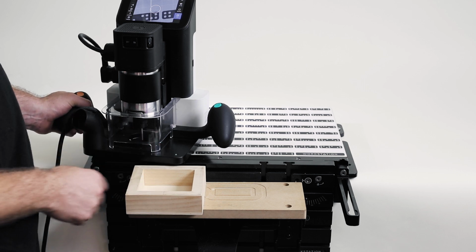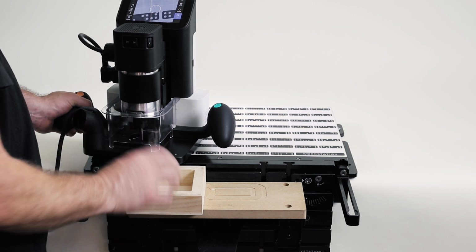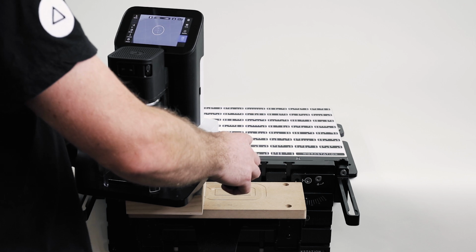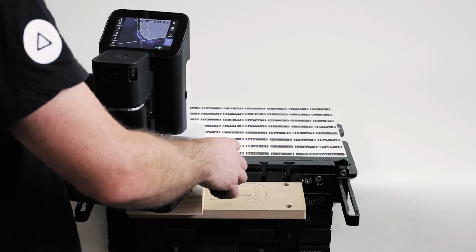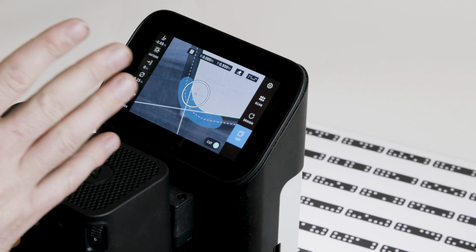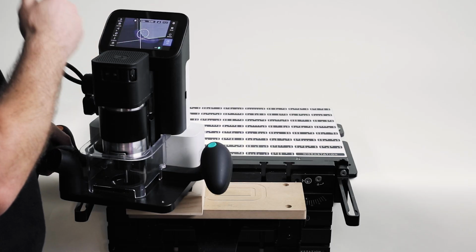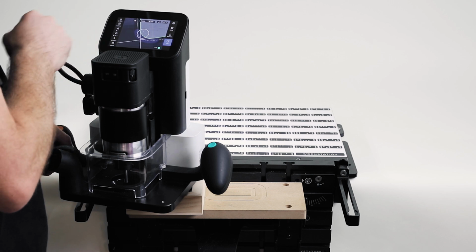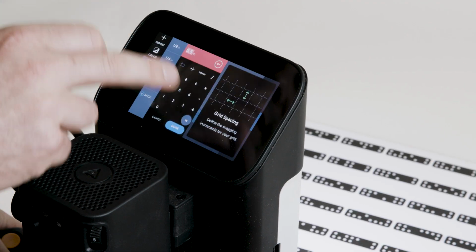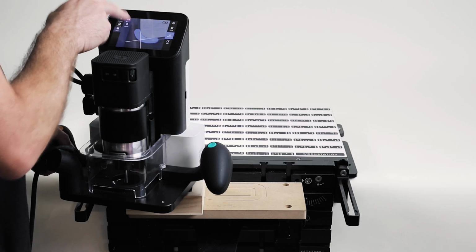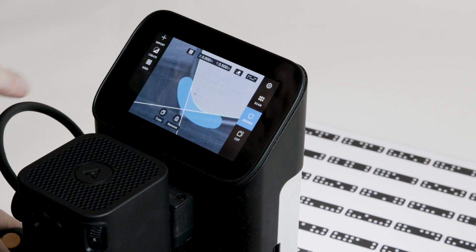So that could round that corner very quickly and easily using grid and making the most of quite coarse grid increments. The same applies if you're on a floor or something like that. There's a reasonable chance you're not going to want these tiny little grid spacing. So if you're wanting to place things on, say, foot increments, the good news is I can go back here and go modify and set this to 6 inches.